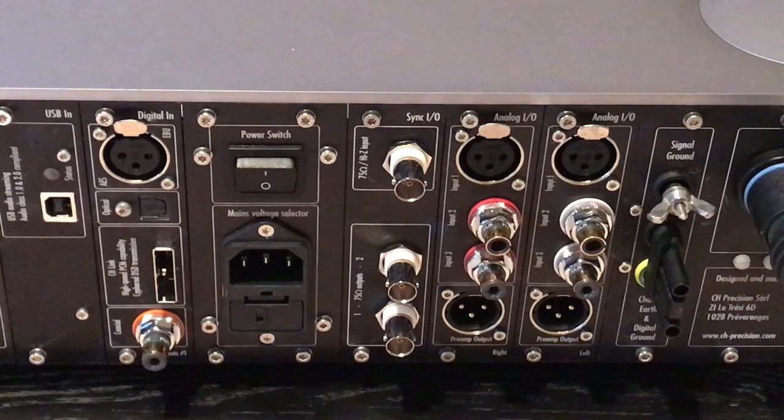If you own a C1 DAC and D1 transport, you can easily improve performance by adding clock sync cards to both units. The clock sync cards easily install into the backplane of each unit. Note, the clock sync card has a BNC connector at the top and two at the bottom. The topmost is clock in, and the two at the bottom are clock out. You can use your C1 as clock master to clock your D1. You'll need a clock cable to do this.